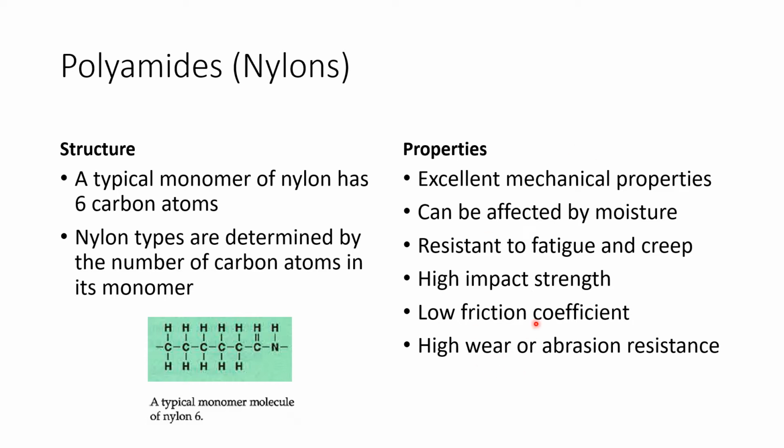When you look at their properties, they have excellent mechanical properties, but they can be affected by moisture. Moisture is the enemy of nylon. They are resistant to fatigue, stress, load and creep. They have high impact strength, a low friction coefficient, and high wear or abrasion resistance.